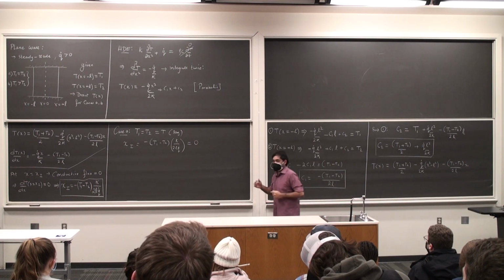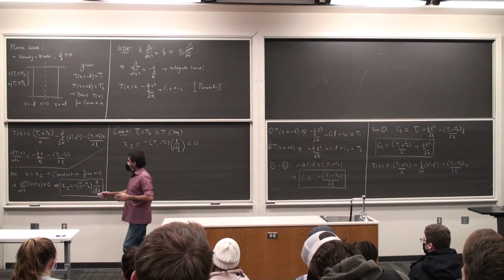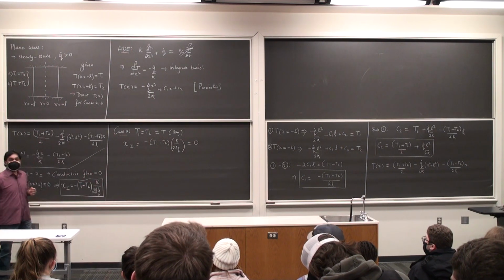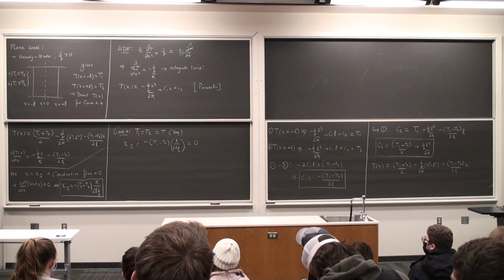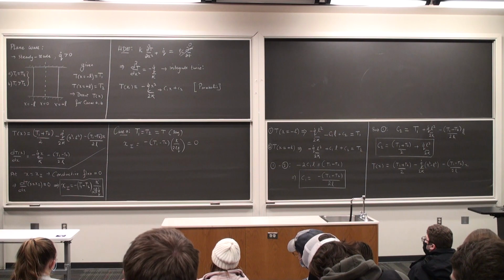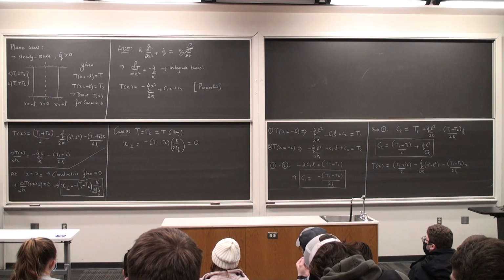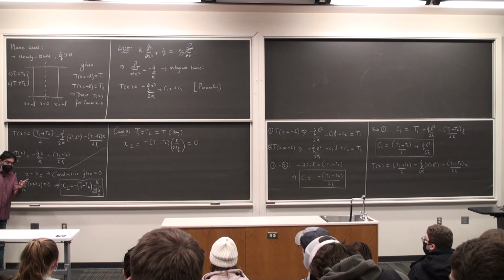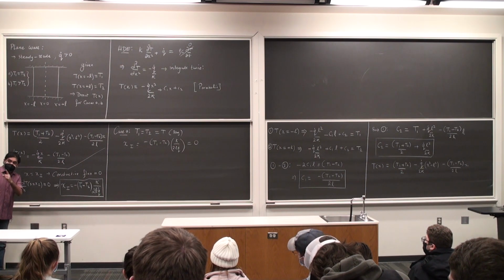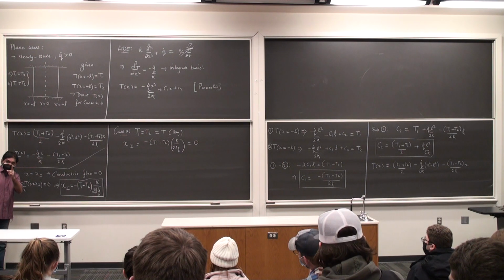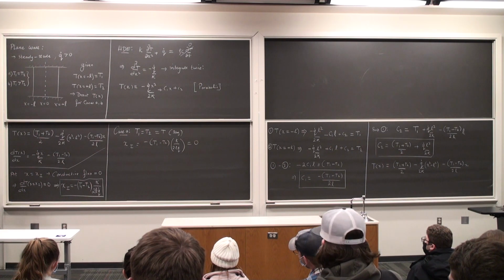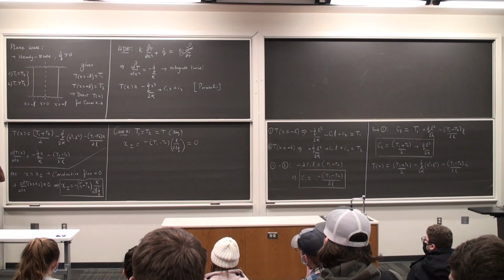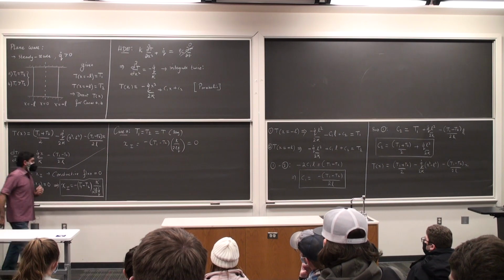So you already solved the problem in your mind. Let's do the math together and let's figure out, without believing in ourselves, what does the math tell us? I start off by looking at the derivative. The key thing is the derivative. If the derivative at x equal to minus L is positive, and the derivative at x equal to plus L is negative, then I have the situation that you just described, where x equal to 0 is insulated, and heat is transferring out from the center onto the left and the right sides. Let's see if that is the case.